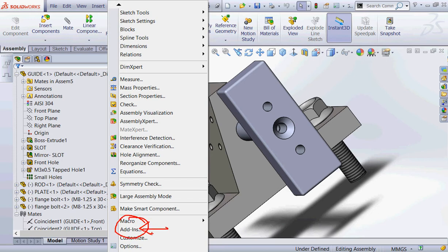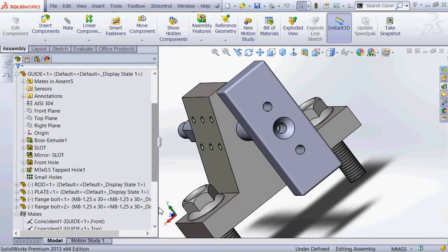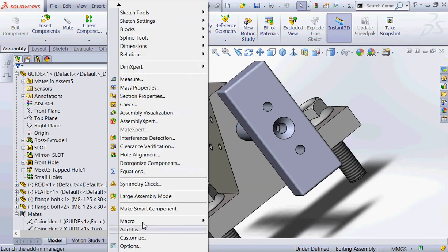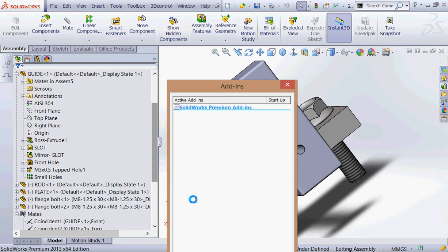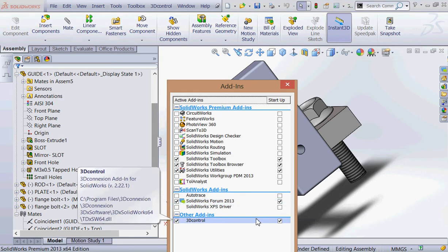It just eliminates a part, right? It eliminates a couple of parts, so that reduces your assembly time, right? It reduces your part count, which everybody likes, because you don't have to deal with ordering those parts and keeping inventory on those parts, right? I'm not saying that you have to do it that way. This is just one way, right?